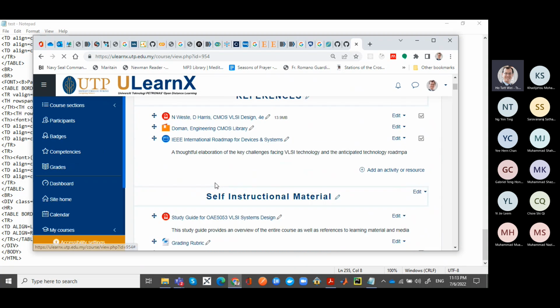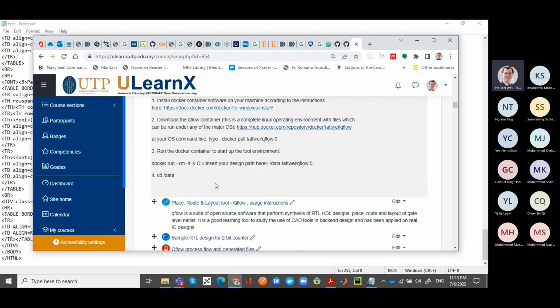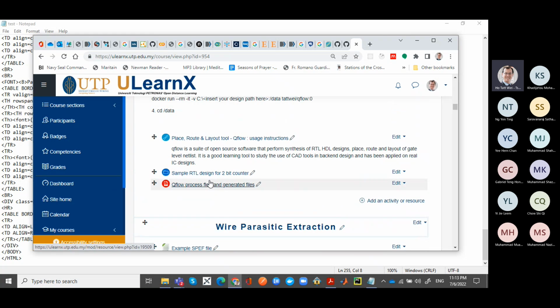And the goal here is then to help you to understand how from that model of the fab file that you get from the fab, that text file, you can actually convert that into the RC, the resistance capacitance model that you use to estimate the delay. So you can actually just get a parameter there called the fan-out of 4 inverter delay. So when you look at the logical effort, that's where we will look at how to do that. You can get a realistic estimate of that delay from that technology and use it to do back-of-the-envelope estimation of the critical path of your design.